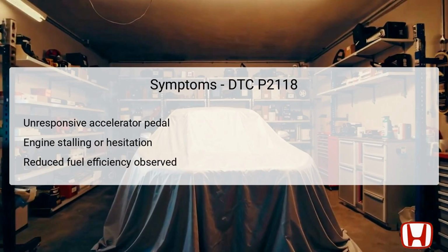Several symptoms can manifest if DTC P2118 is present in the Honda Accord. One of the most noticeable signs would be an unresponsive accelerator pedal, where pressing down does not yield expected engine response. This could lead to engine stalling or hesitation during acceleration, causing a risky driving situation.